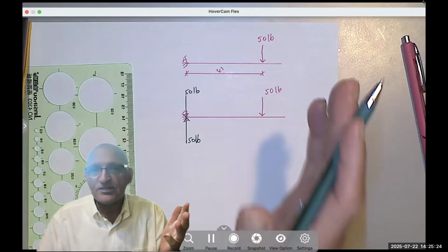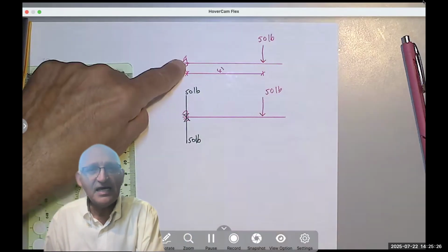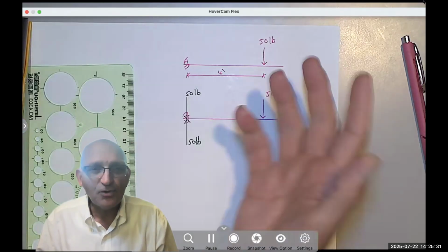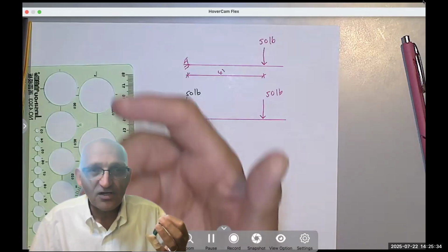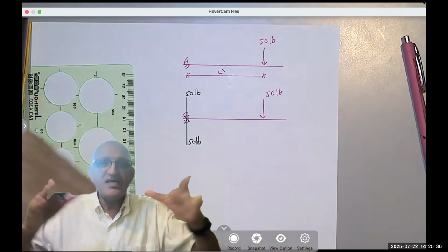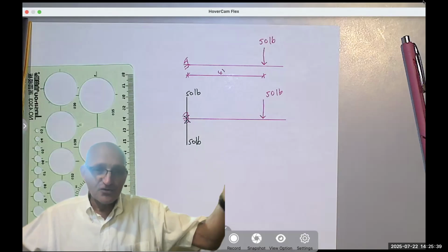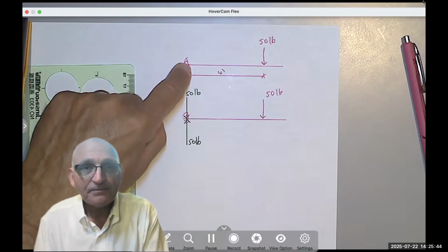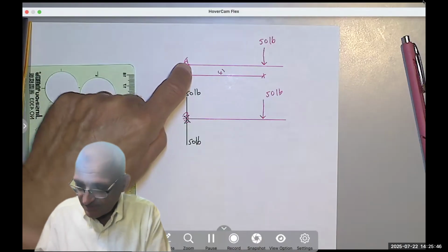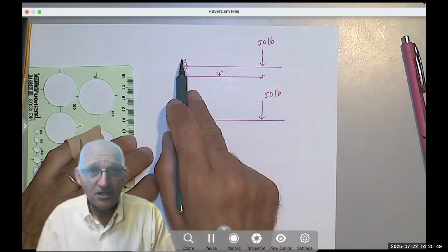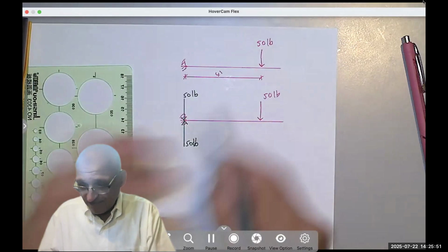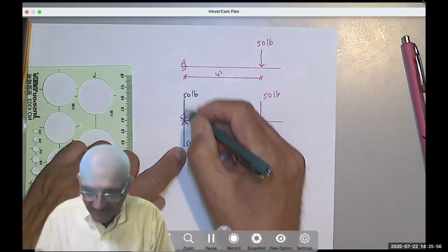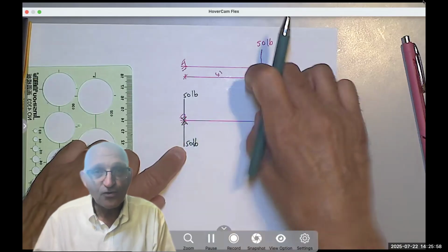That was just a force, but it wasn't applied at the support. So I don't know how do I design the support? What forces act on it? And when I say force, I use it in the larger meaning, forces and moments. Okay. What forces does this support feel? In order to see it, I'm saying, oh, I wish the 50 was here. So I say, yeah, okay, move it. You say, but if I move it, I change the system. Okay, move it by adding and subtracting the same force.